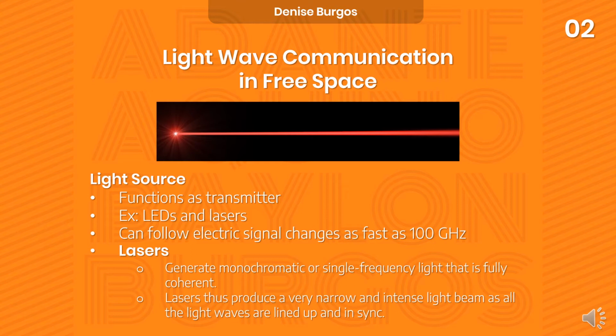It also makes optical communication more practical. The high-intensity and single-frequency light source is a narrow beam of light with a specific wavelength or color. It can penetrate atmospheric obstacles better than other types of light can, thereby making light beam communication more reliable over longer distances. Because of the narrow beam of light, transmitter and receiver must be perfectly aligned. Misalignment produces loss that will be discussed in another section of this presentation.